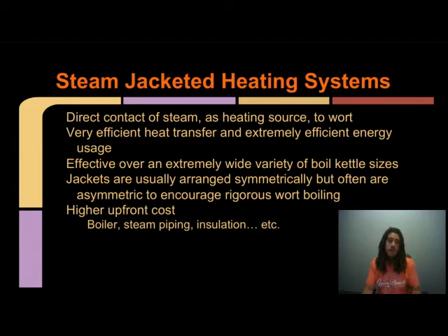There are also steam jacketed systems. Steam jacketed systems are very efficient because they give you direct contact of heat to the wort. There's a huge transfer because the surface area is large. So it's not just a direct heating source. It's all over. It usually surrounds the tank and the bottom, so you have heat coming from everywhere. So it's very efficient heat transfer and extremely efficient energy usage once built.